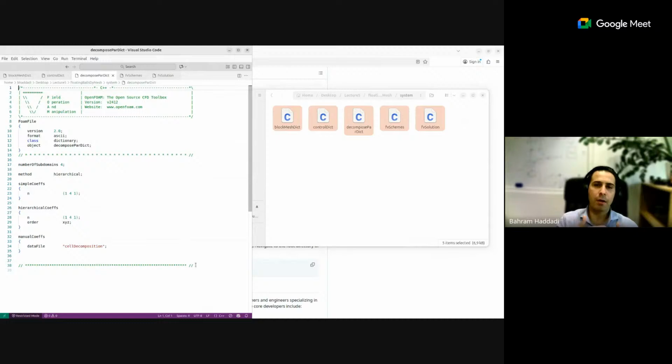So the solution is parallelization also on the CFD side. Basically, this parallelization also works on the unresolved case. You can apply it to all of them. What we do here is break our geometry into 4 subdomains and do parallel MPI calculations on that. For PhasicFlow Plus, the CFD is always parallelized using the MPI approach. But for the DEM, the parallelization depends on the type of PhasicFlow compilation that you have.